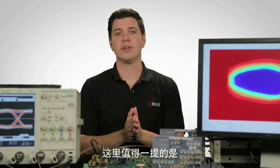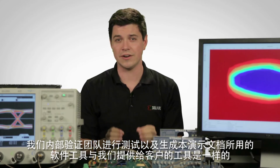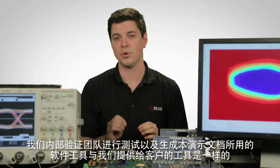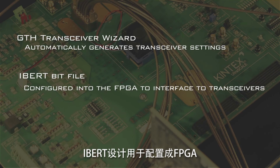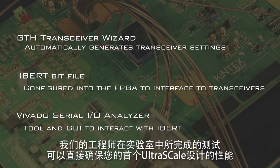It's important to note that the software tools used by our internal validation teams to do their testing and to generate this demo are the same tools we make available to our customers: the GTH transceiver wizard used to generate settings, the IBERT design configured into the FPGA, and the Vivado serial I/O analyzer to interface with that design. This ensures that all of the testing our engineers do in the lab translates directly into guaranteeing performance in your first UltraScale design.